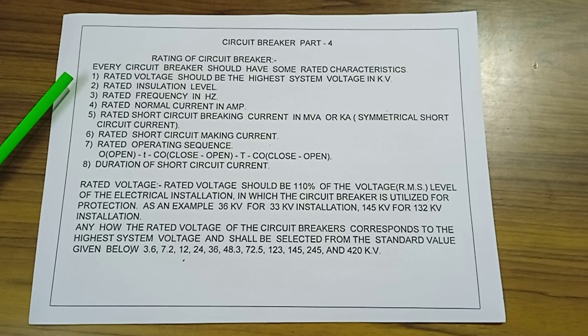First one, rated voltage, which should be the highest system voltage in kV; rated insulation level; rated frequency in hertz; rated normal current in ampere; rated short circuit breaking current in MVA or kiloamps, symmetrical short circuit current. Sixth, rated short circuit making current.